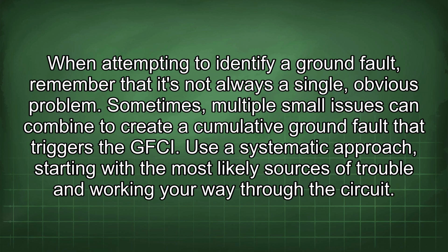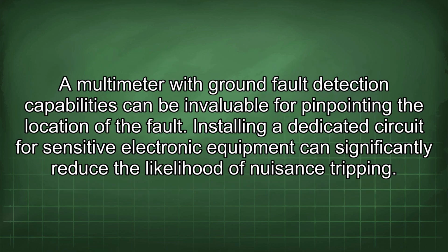When attempting to identify ground faults, remember that it's not always a single, obvious problem. Sometimes, multiple small issues can combine to create a cumulative ground fault that triggers the GFCI. Use a systematic approach, starting with the most likely sources of trouble and working your way through the circuit. A multimeter with ground fault detection capabilities can be invaluable for pinpointing the location of the fault.